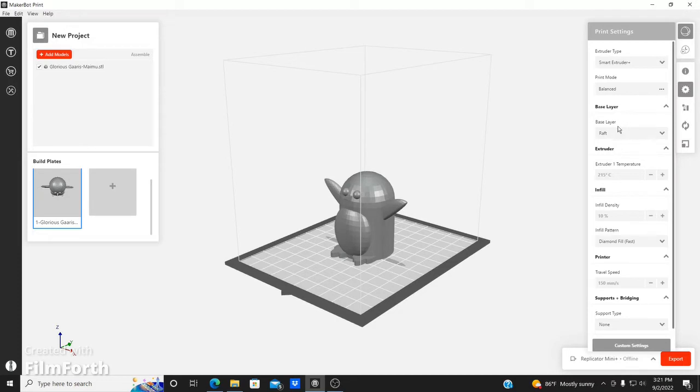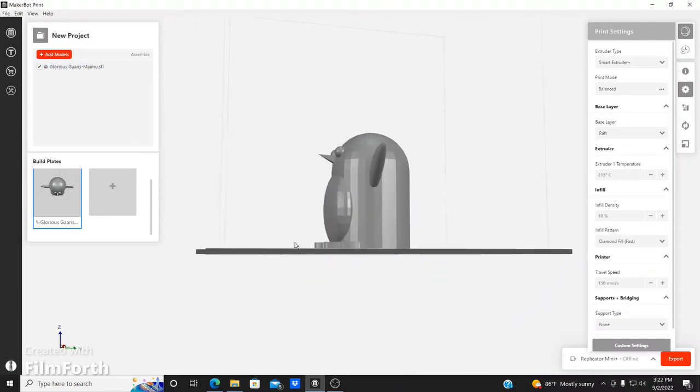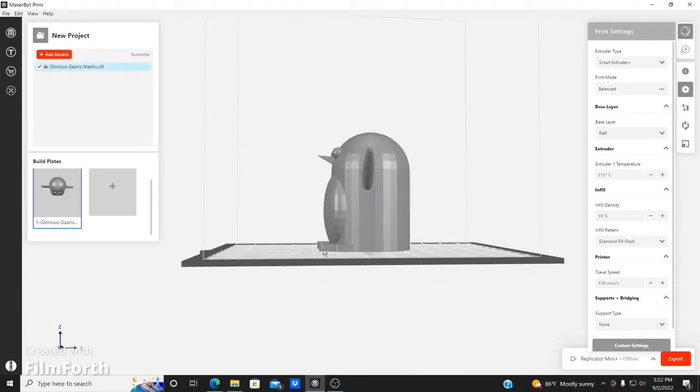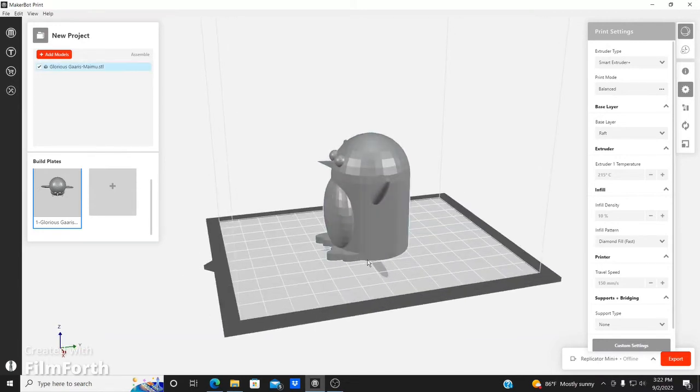The base layer, these ones that we have options, which is the raft, padded base, and padded base with brims. What it means that raft and padded base is used is because if your part is a little bit larger, and it's exposed, like there's no glass container or anything like that, and if there's an environmental impact either from the outside or inside, there might be a chance that your part will fail, that you're printed on the bottom, it'll lift up right away. So it'll come off the plate, and it'll warp itself upward.